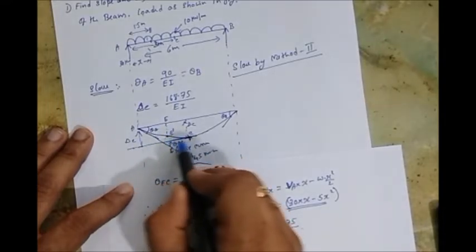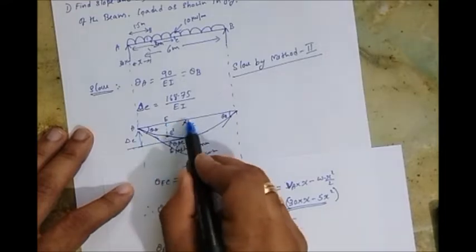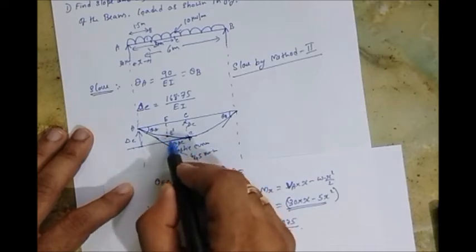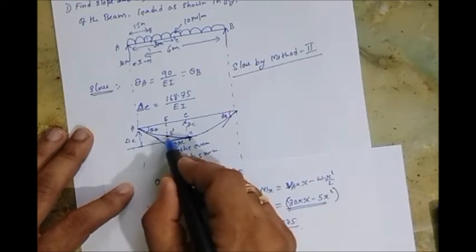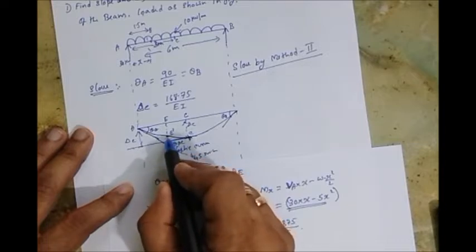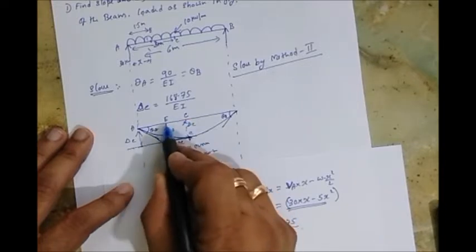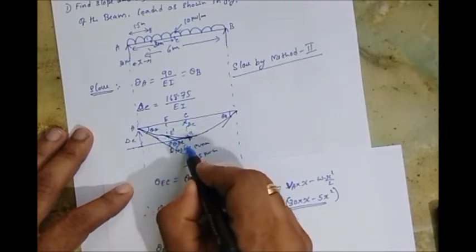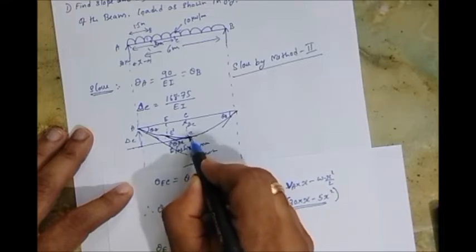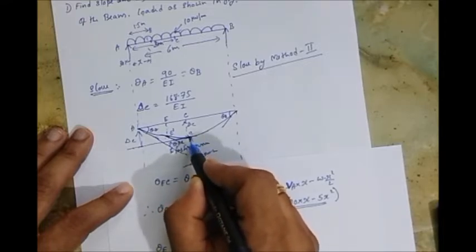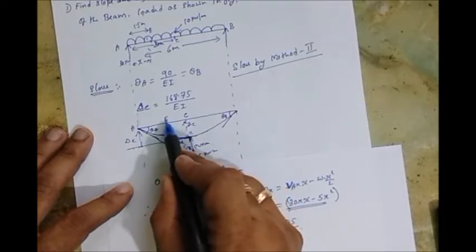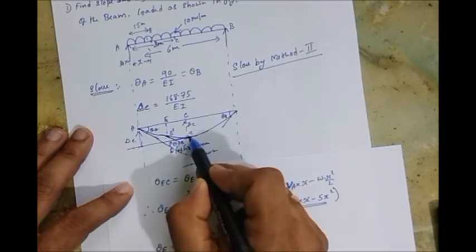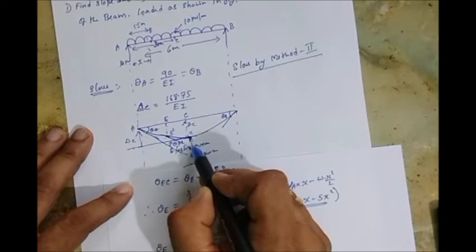So, if you use the two reference points, E and C, how will you get it? If you use the moment-area diagram between E and C about C, you know what you're going to measure? You're drawing the tangent from E and measuring the deflection here. This is not what you're looking for, right? Because if you take the moment-area diagram between E and C about C, you draw the tangent from E dash and measure at this point C. So this is not the deflection you're looking for.